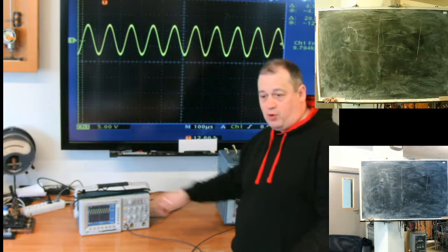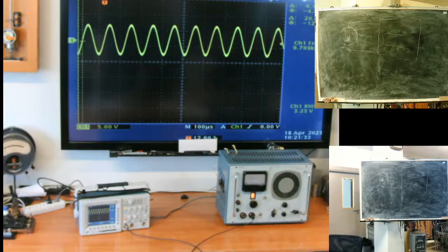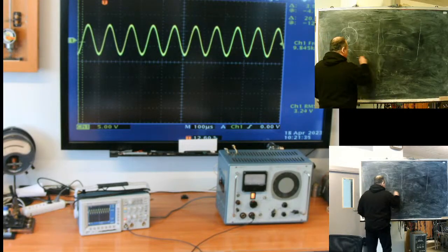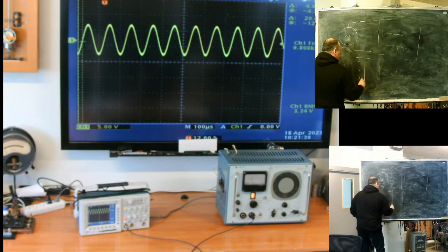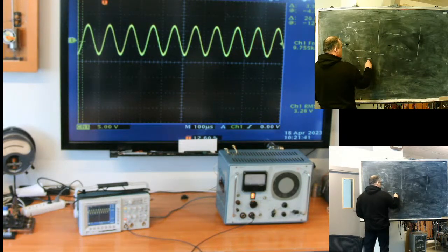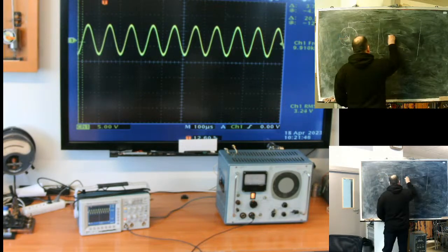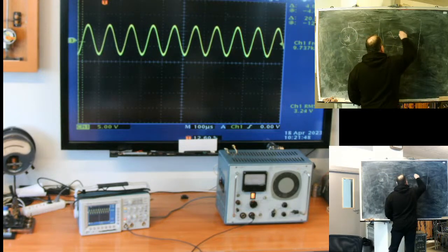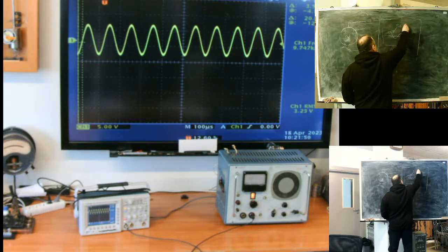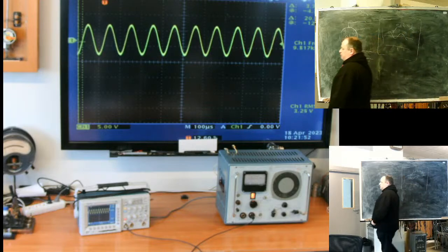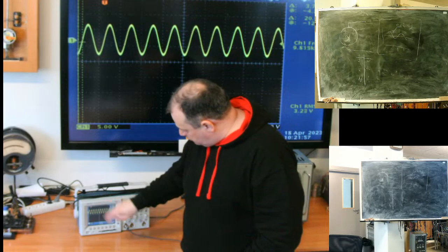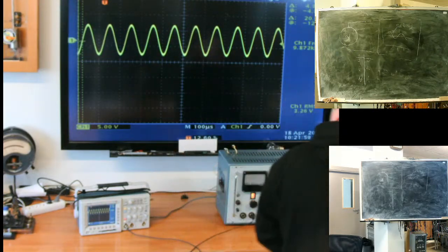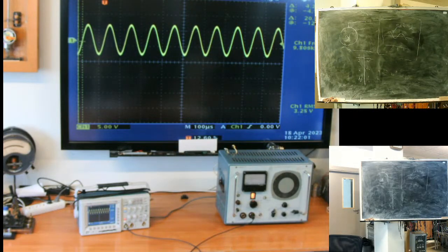What does this scope perform? Sampling. It creates a table of signal values, from 1, 2, and so on, with values like 1 volt, 2 volts. So, in fact, my scope draws the signal as a function of discrete time. The scope is able to take 2.5 gigasamples per second. It's quite a high number.